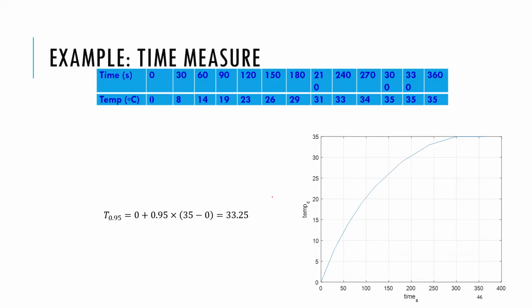But more specifically, given this particular model of a system here, if I want to do a transfer model of this system, what is my steady state value of this system? It goes to 35. So 35 would be there for a step response. And then I have tau s plus 1. And this is called G of S. So what is tau in this situation? It would be 63.2% of 35.